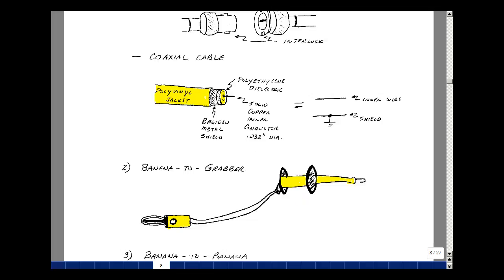We're using a solderless board, and wires kind of pop out of there very easily, so we're going to use test wires and then connect with these grabbers. This type of connector is okay for audio frequencies, but would not work well at radio frequencies.